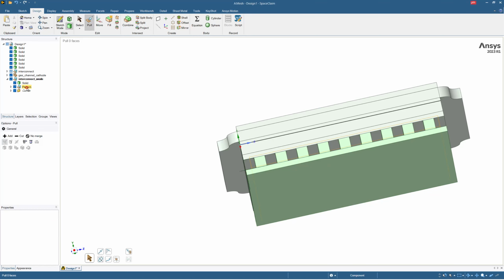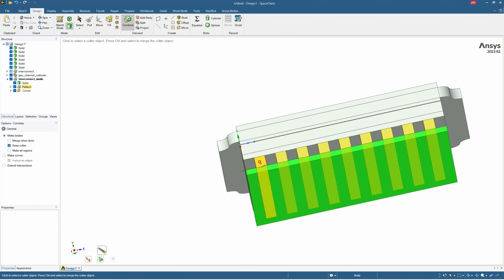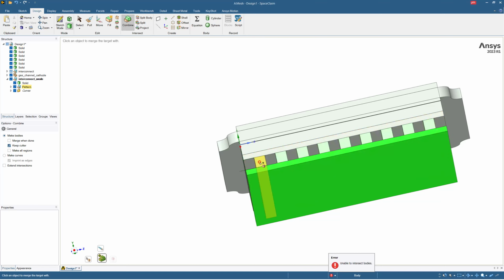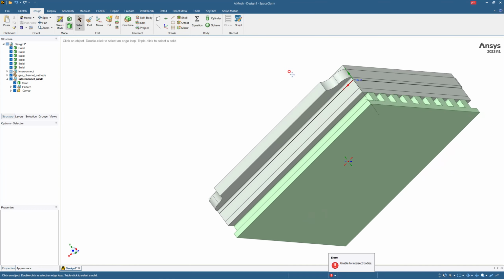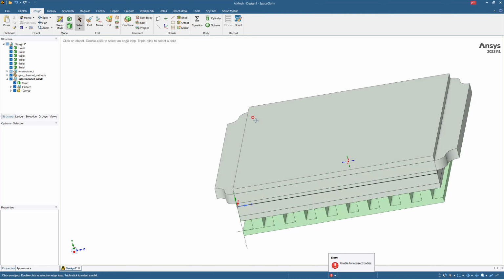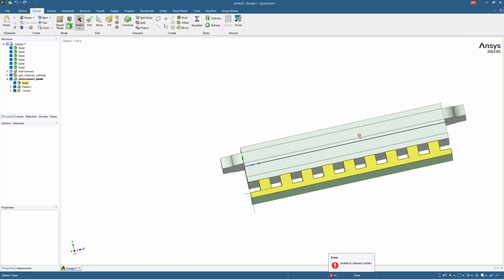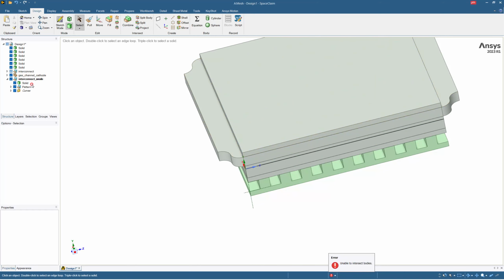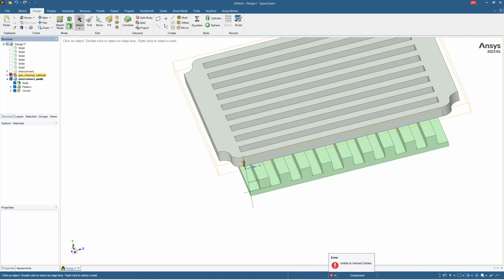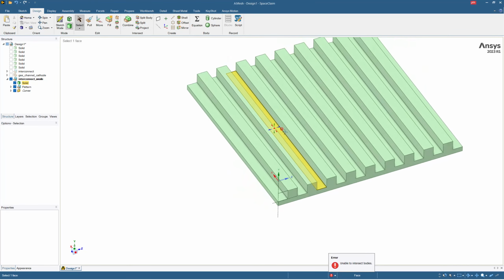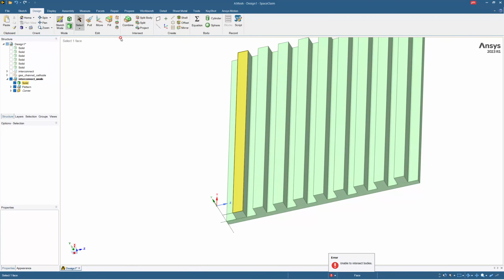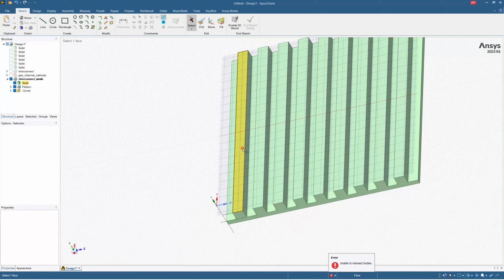Now if we want to make this solid surface combine, now as you can see we have again the interconnect model for the anode side, and we have space available for the gas channel at the corners. So we will uncheck all, we will check the visibility except for the interconnect, and now on the top plane we will draw the manifold, the gas channels.